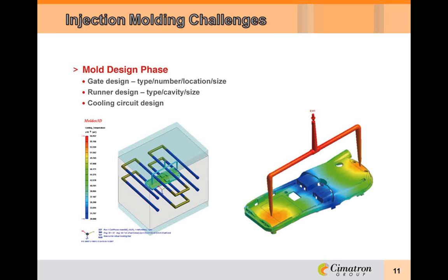The primary tasks of an injection mold include the accommodation and distribution of the melt, precise temperature control to properly solidify the material, and ejection of the molded part. Additionally, a mold has to provide good tooling or steel conditions and mechanical functions such as slides and lifters, all while holding tight tolerances on the part after the warpage and shrinkage of the solidification of the material. This places an enormous challenge on the mold designer.